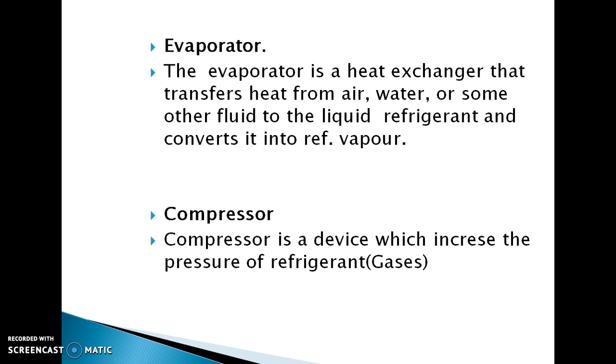The evaporator is a heat exchanger that transfers heat from air, water, or some other fluid or objects to the liquid refrigerant and converts it into a vapor refrigerant. So evaporator is basically a heat exchanger. It can be tube-in-tube type or tube-in-shell type as per the required applications.